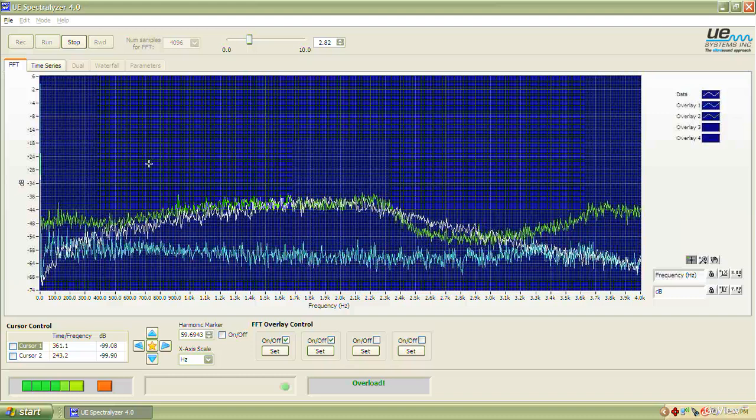Now the FFT window here is none. I believe I chose this was for electrical, but I would rather have it as Hanning, the most common type of window. These are slight changes in the way it works. If you're not familiar with these terms and don't truly understand FFT, leave it at Hanning. That is the most common window I know of for FFT, and that's what I've been teaching you on for the most part here.